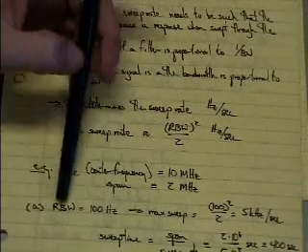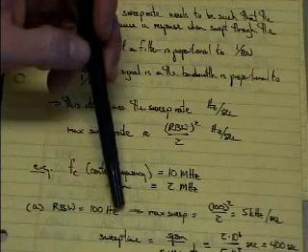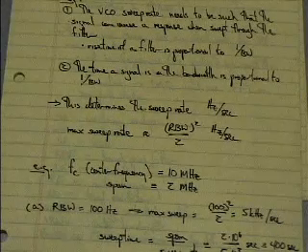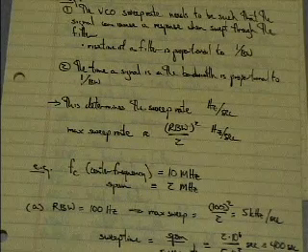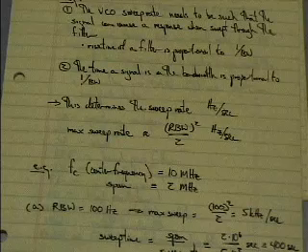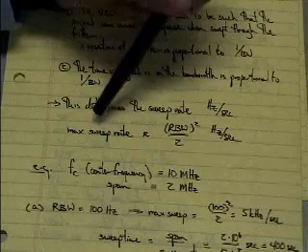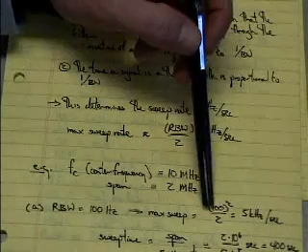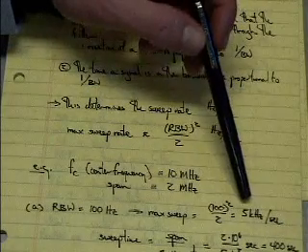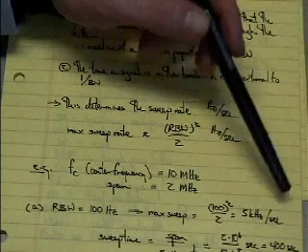Well, first of all, let's say I set my res bandwidth to 100 hertz. That is, I want to be able to distinguish two frequencies that are as close as 100 hertz to each other. Using our maximum sweep rate calculation, that would be 100 squared divided by 2, telling me I can sweep as fast as 5 kilohertz per second.